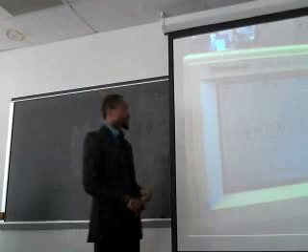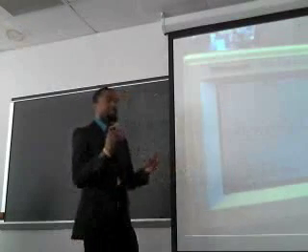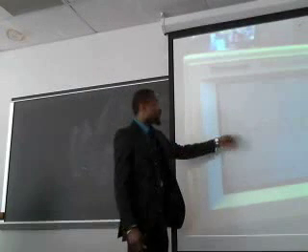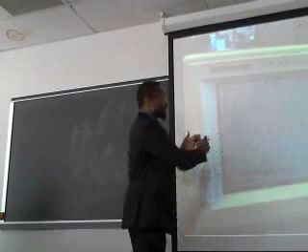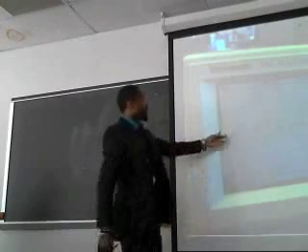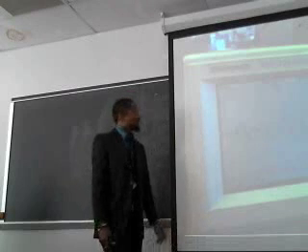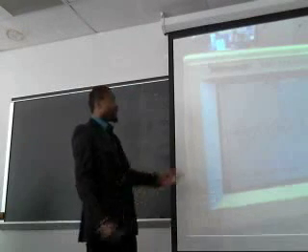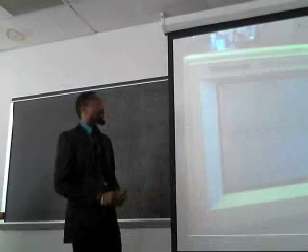And this is the output. Basically, this is just for 2 phases because with the scope in the lab we cannot test 3 phases, but we tested the output for the 2 phases. This is the result. We have the sine waves. As you can see right here, they are shifted. You see the 120 degree shift from each other. So this is the simulation for the 2 phases. Because we cannot really test with this scope, we cannot test 3 phases of the system.